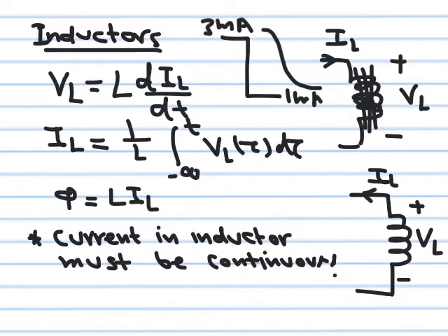Okay. On the other hand, the inductor voltage can change abruptly. There is no problem. It can change direction suddenly from 3 to -3 or whatever the case is. This can happen for an inductor. So this is the opposite of the capacitor. In the capacitor, the voltage will have to change smoothly, but the current can reverse direction instantaneously. Here, the current will have to change smoothly, but the voltage can change its polarity instantaneously.